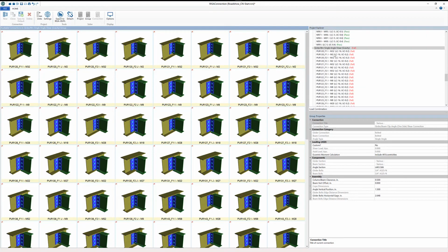And we can see this really pretty simply, in fact, that we have a controlling load combination in most cases to be load combination 16, but we have a unity check that's under 1, so at a 0.2, and it's still failing. So this tells me right off the bat that the failure is not from a particular design limit state, but one of a geometry restriction.